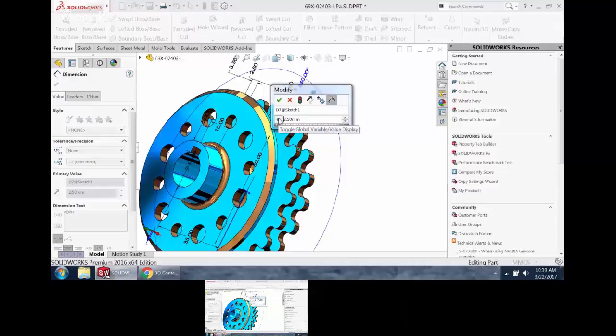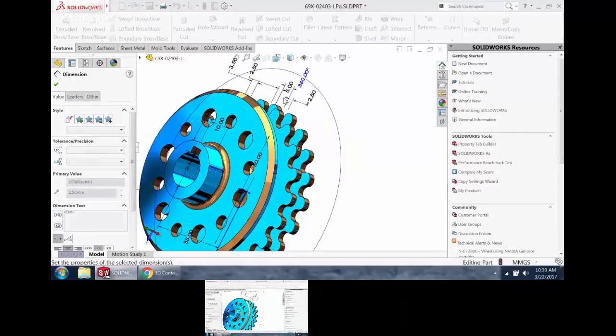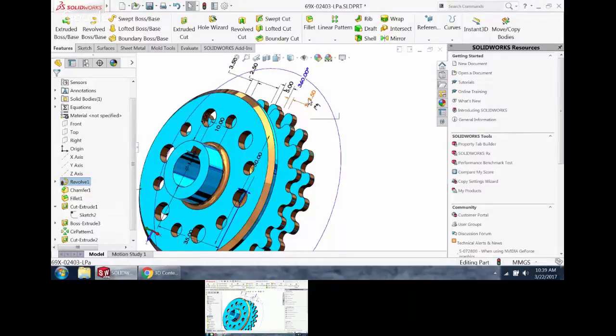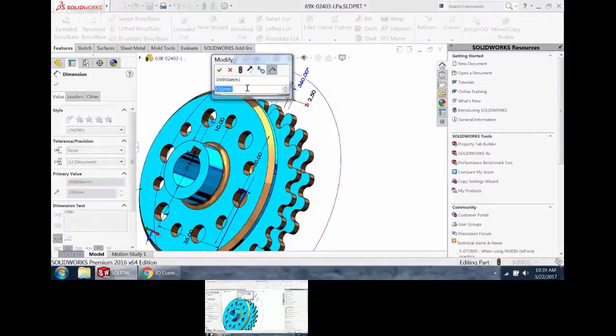And now I've got a variable called wall. See, when I bring up the dimensions for this, now this has a sigma in front of it. I can continue creating other ones. Once I start typing it in, it'll show me there's one called wall. If you pick it from that list, you don't have to type in the quotations. It'll do it itself. If you do type it in yourself, you have to put in quotation, W-A-L-L, quotation.